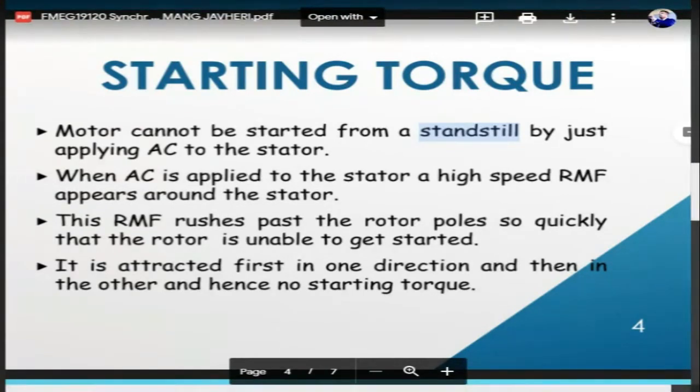But the rotor needs to be magnetically locked with it. And how will it lock? As per the design winding diagram, we get to know how many north poles and south poles there are, and accordingly we get the connection, or magnetic locking, between the stator magnetic field and the rotor magnetic field.